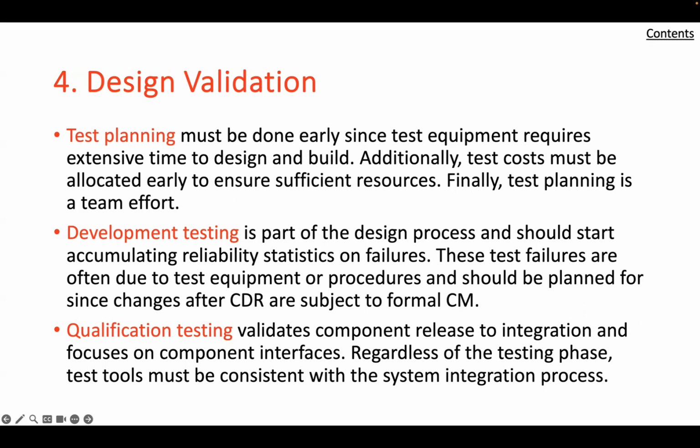These tests also focus on the features of the design that are subject to severe environmental conditions such as shock, vibration, external radiation, and so on. For components subject to wear, such as those containing moving parts, development testing can also include endurance testing, usually performed under accelerated conditions to simulate years of wear in a matter of months.